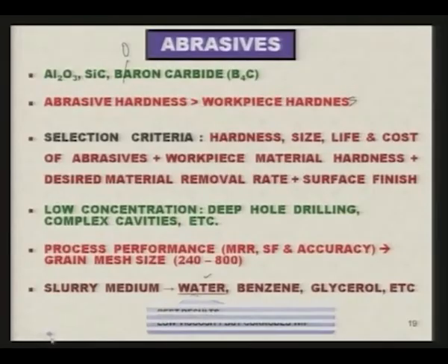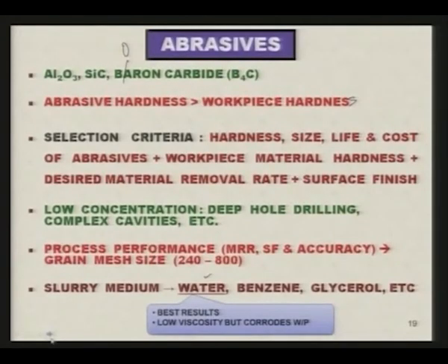If it has high viscosity, then it may not be able to reach those fine cavities or fine details on the machined component. Water gives best results because of low viscosity, but the problem with water as carrier medium is that it corrodes the workpiece. So, one has to take this also into consideration.